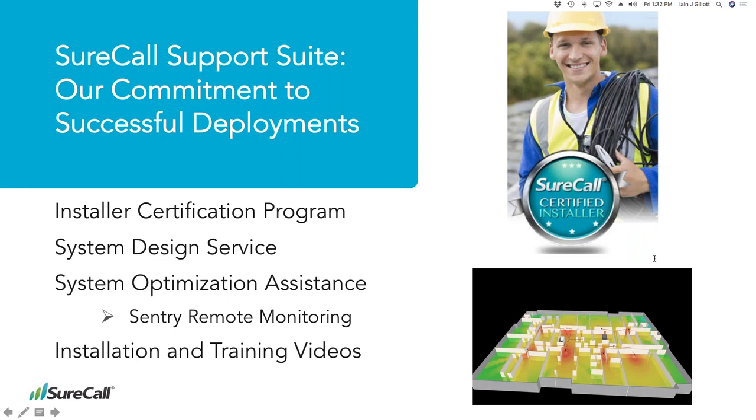And once we have all that information from the site survey, once the installer has completed that, we offer a free system design service as well. We take those answers from that site survey, take the floor plans, and we create a design, much like the one you see here on the bottom right-hand side of the page, a heat map through IB-Wave, and it lets you know exactly what you could expect after the system is deployed. Where you did not have coverage before, you should have coverage after the system has been commissioned.